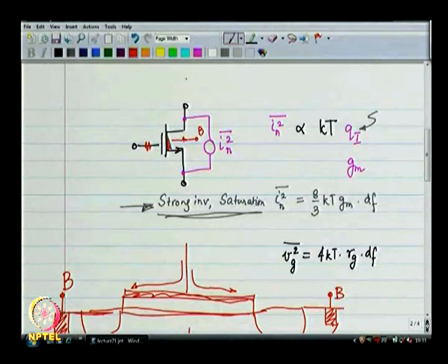Similarly, if you have a contact resistance on the drain, a contact resistance on the source, then those also will add certain amounts of noise voltage. Okay. So, we will treat all of those like resistors. Now, when you are treating all of these like resistors, do not forget the parasitic capacitances that you have, okay. Do not forget those are important, because a lot of this noise is going to get filtered out by the parasitic capacitors.